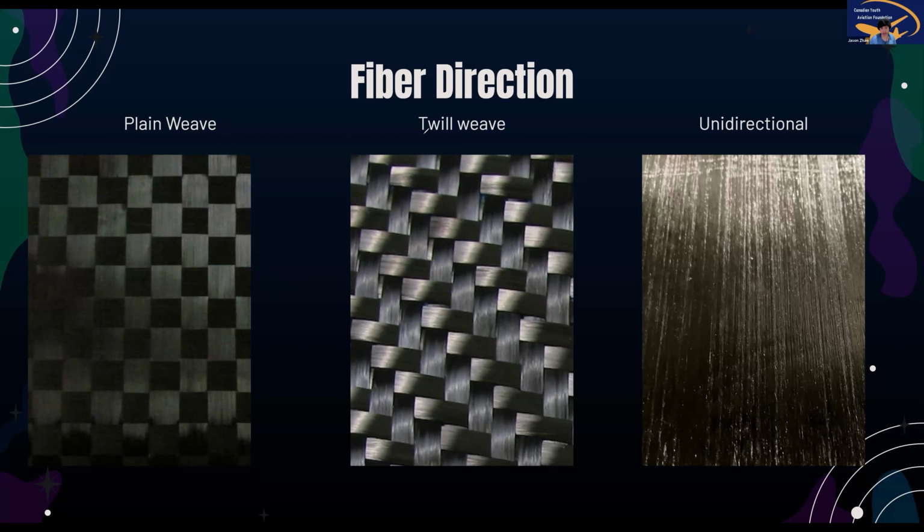So this is something called a twill weave in the middle. So instead of having a checkerboard, now you have little triangles almost. This makes it a lot stronger in the diagonals. You can basically pull on the diagonal without breaking it. So this is just a better version of the plain weave, but it's slightly more expensive.